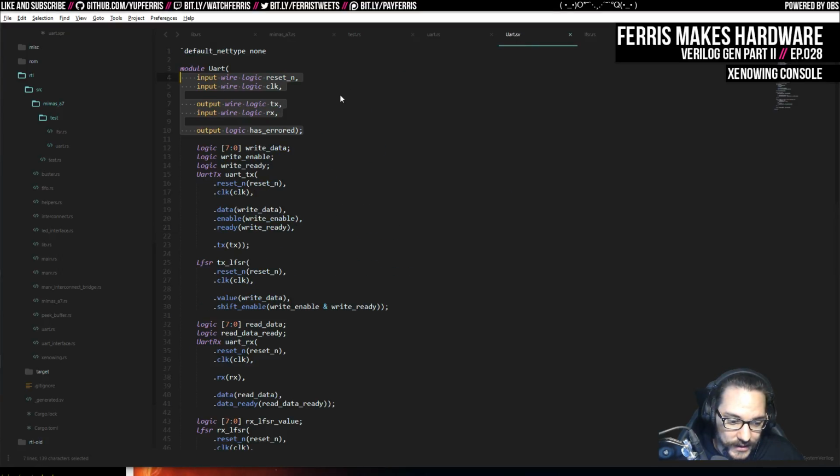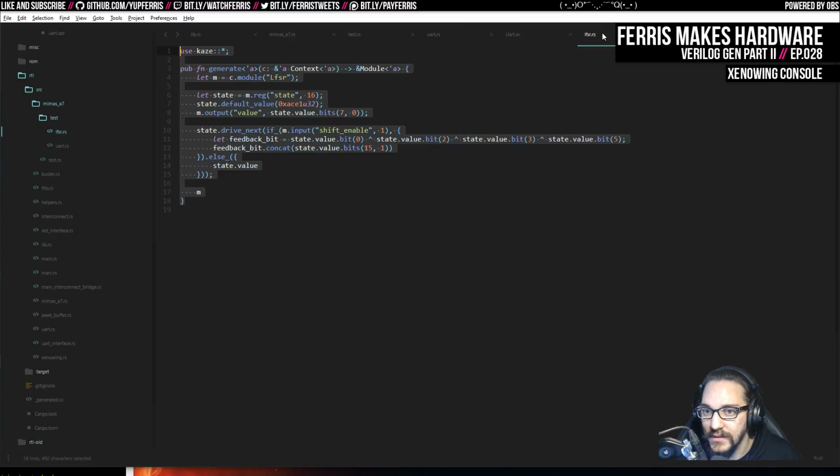So what I want to do is come up with sort of an idea where you can have, for example, Spinal HDL and Chisel have these things that I think are called bundles. And then those are essentially just groups of signals. And the idea is that each module has an IO bundle, which defines its inputs and outputs, or declares them, and then you have to drive them like you would an input and output to a module instance.